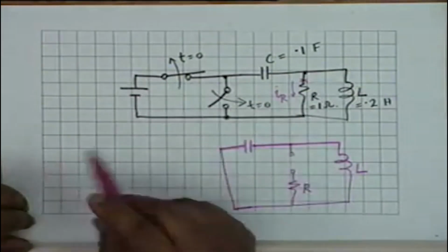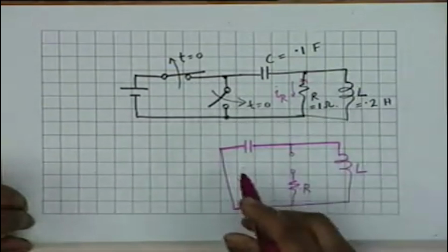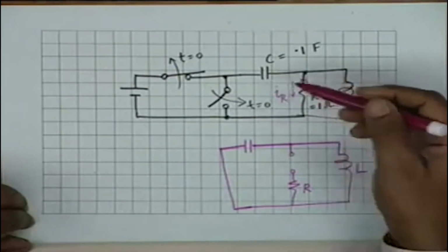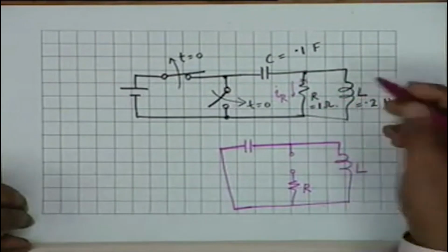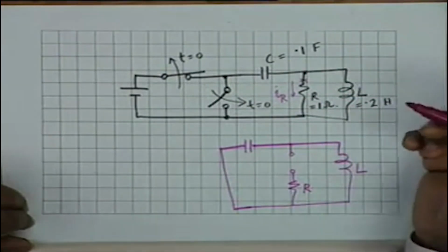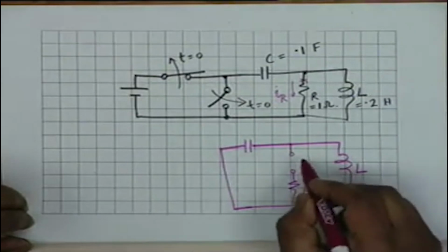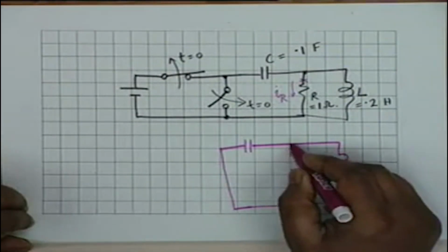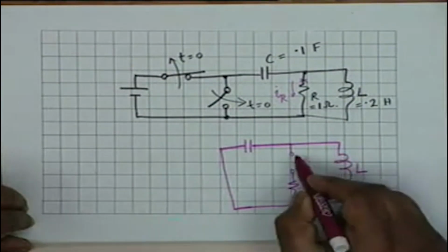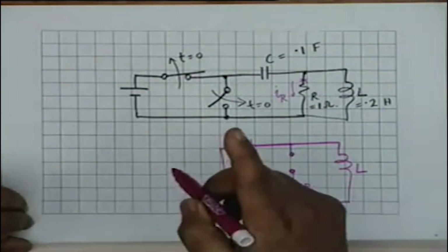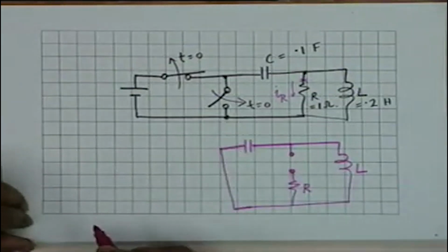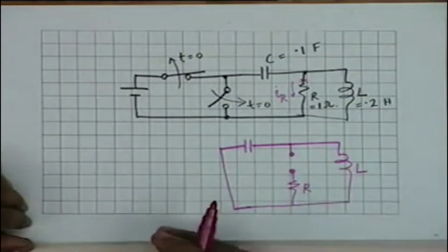That is part of the initial condition which you can find out. That is Vc0 minus equal to Vc0 plus, and IL0 minus, which is equal to 0, equal to IL0 plus. But since we are trying to find the current through the resistance R, we find the impedance between these 2 points. We make an artificial break, find the impedance, and then find its zeros.